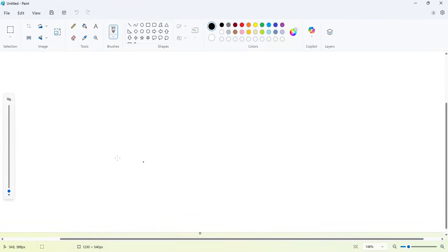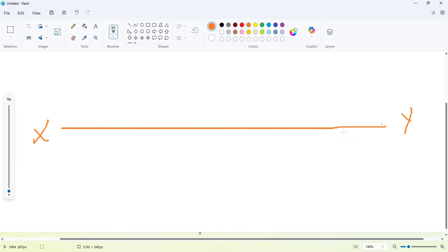This projection is done in 3 steps. Again, we have to use this XY line. First condition will be for the resting edge or the plane which is resting on HP. So suppose this is a pentagon. While resting on HP, it appears like the actual pentagon. The original dimension will appear from the top view, and front view will be from the front. Front view will appear as a straight line, which should start from this point to this point.